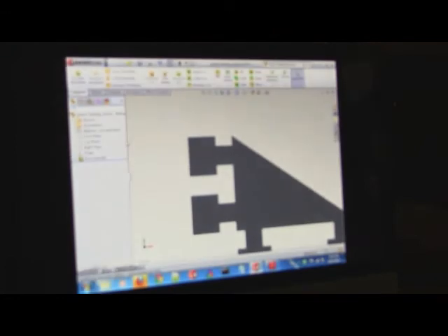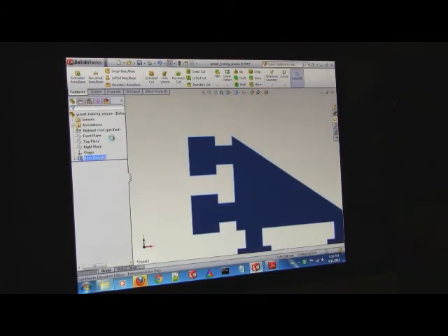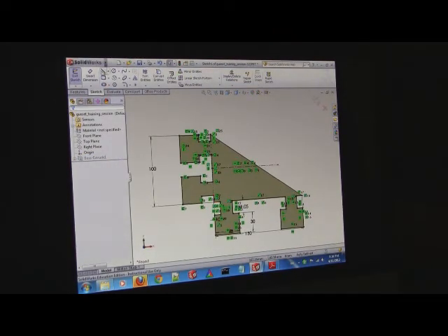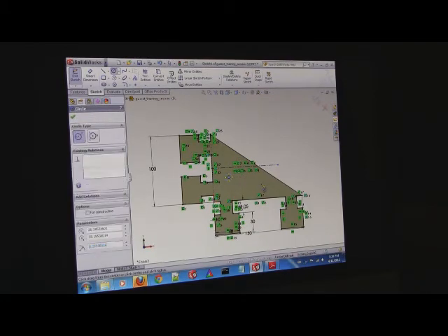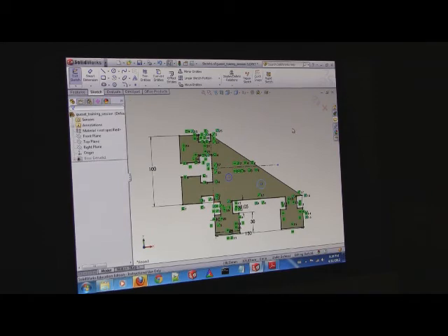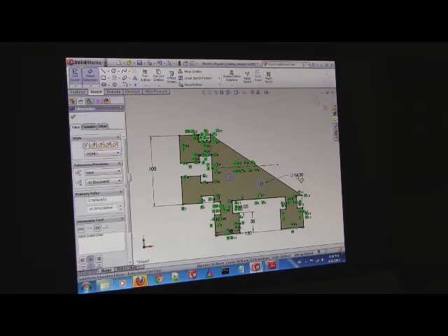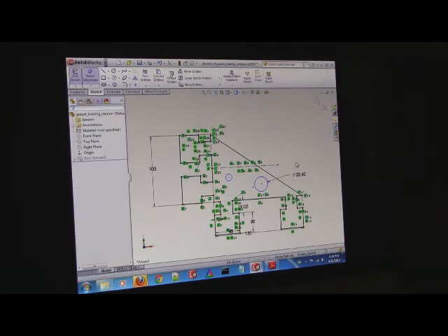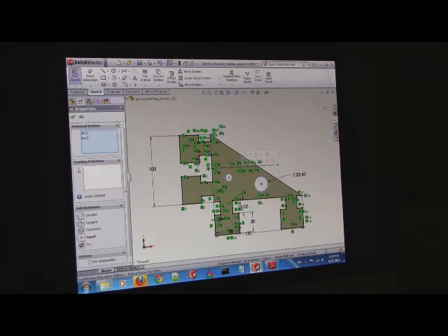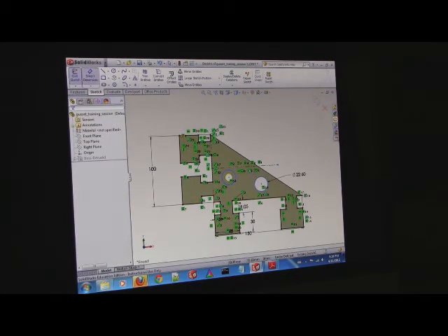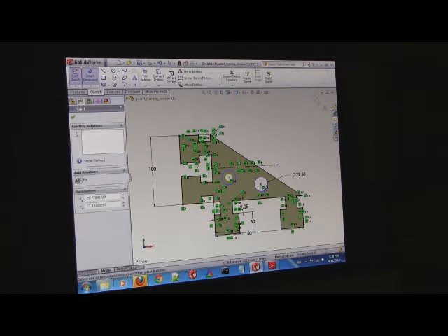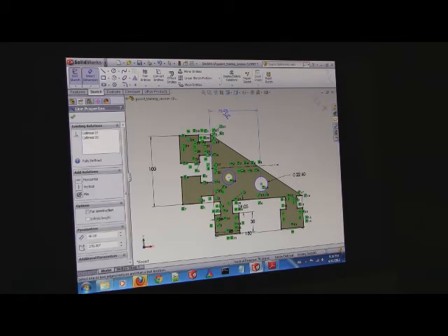Okay, everybody go back and edit your sketch. The only last thing we're going to do is add two circular holes. So take a circle and just make two of them. Here's another trick. So smart dimension one of them to 22.6. And I want them to be the same diameter. So select both circles, hit Control, and press equal. They're now equal.